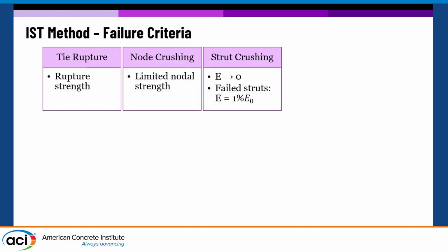So if your model for concrete is not perfect, as node sizes are not perfect, you basically just have to ensure with your design that those elements do not fail first. That's all you need to do. Your reinforcement is yielding first. Here it's completely different. You don't want your reinforcement to break. You have to model concrete in compression, and therefore the size of the node in the compression zone becomes so important, because based on the size, the failure value changes. Everything changes, right? So now it's clear to me.